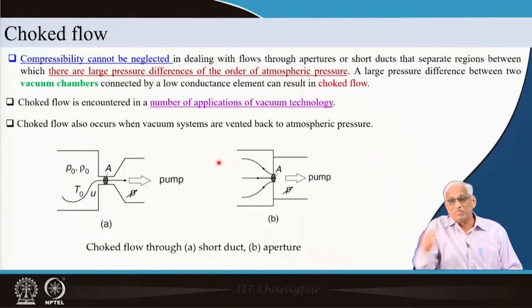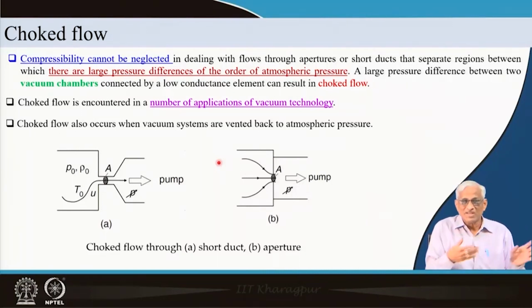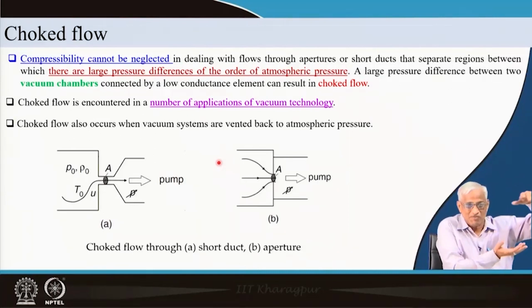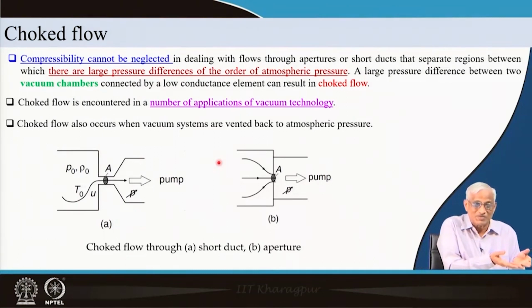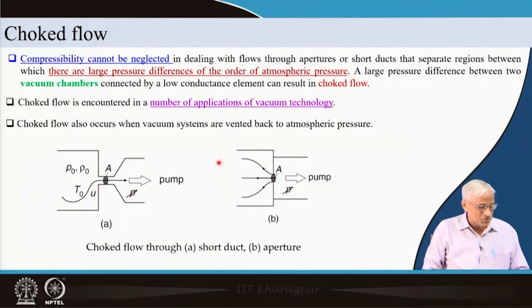And sometimes, so that debris does not go into the pump, we may have to initially choke it and slowly open that, so that after some time it is freely evacuating. When you are connecting huge vacuum pumps to relatively smaller volumes, you may enter into such a situation where some particles may go there, even some costly material inside your process may go there. Such situations are to be avoided, so you have to intentionally create choked flow.